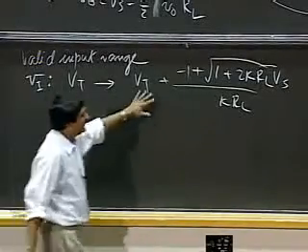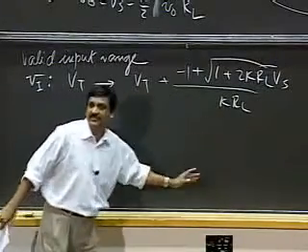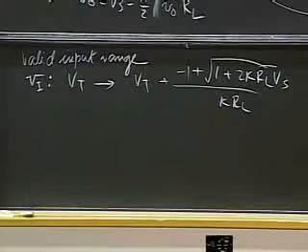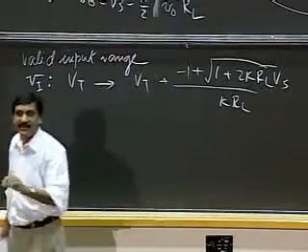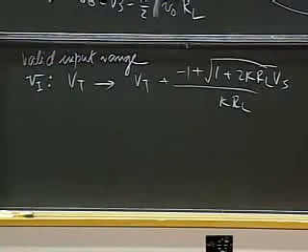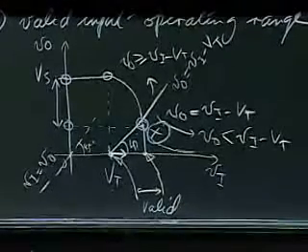And again, remember, I won't dwell on this equation because you will get a different set of limits for other devices, for other circuits containing a MOSFET, or for other outputs that one may be focusing on. What's more important here is not so much the results that you see, but the process that I've gone through. How did I get here? The way I got here was, I looked at the graph and said, look, the MOSFET is in saturation in that regime, and I'm finding the bounding point of the regime of saturation operation.